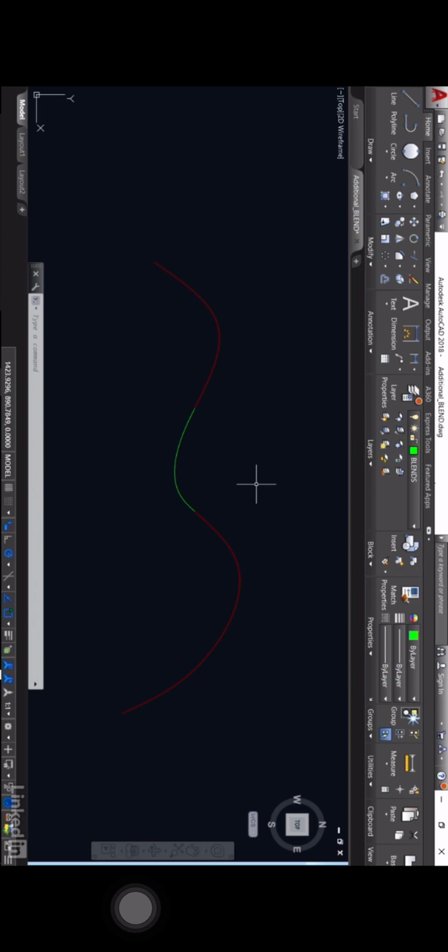And the reason being is sometimes you get weird and wonderful splines, different curves, different angles, different control points. And the whole idea of these blends is that it joins them neatly together so that the curve follows through from one end to the other. So that's how you utilize the blend command in AutoCAD with the different continuities, tangent or smooth, so that you get a nice smooth transition between two individual splines in an AutoCAD drawing.